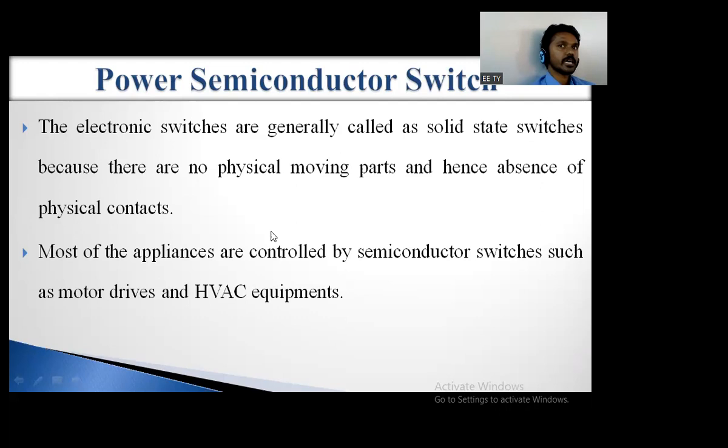For example, we have speed control techniques. Armature resistance control method. Is it right? And field flux control method. Do you remember the speed control techniques of DC motors: the armature resistance control method, the second one is the field flux control method, and the third one is the armature voltage control technique.